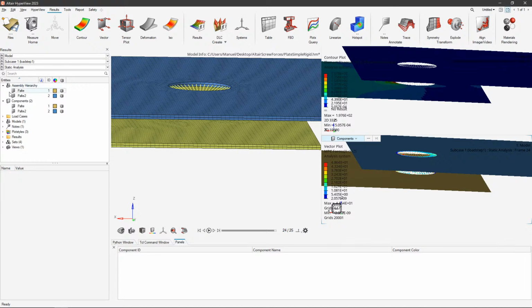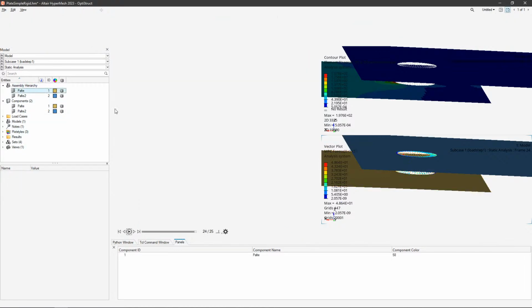And we could also do something like a script in TCL, which converts an arbitrary model to have different properties. By just looking at the components and duplicating the properties and assigning them, it will be ensured that every component has a different property. Okay, now let's do that.